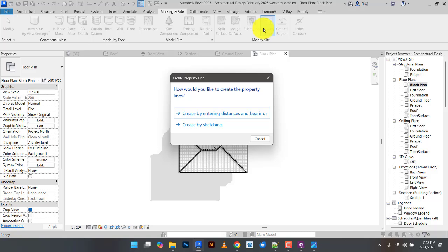If the client doesn't have a site plan, it means you have to sketch it. You go there, you measure, you come and put in a value. So you click on sketch. Sketch means you just draw a line. That's not accurate. You can do solar analysis and all that, and the software will do it based on the sketch you give it, but it will not be accurate.